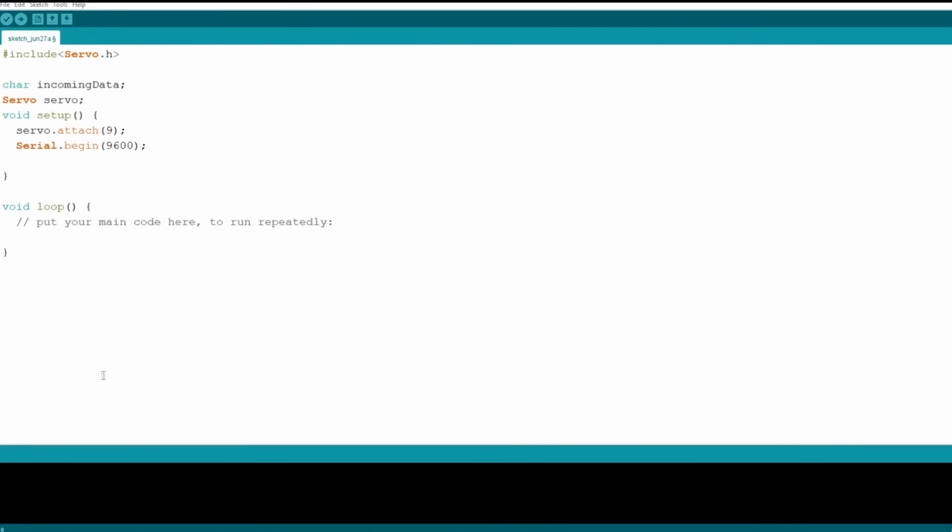And now let's set the starting angle of our servo motor. As you know, we need to set our arm to full open, therefore we need to set it to 180 degrees. If we want to control our servo motor, let's first call our servo object and put a dot, and call our write method. Also open and close parentheses and put a semicolon, and inside the parentheses let's define the angle as 180.